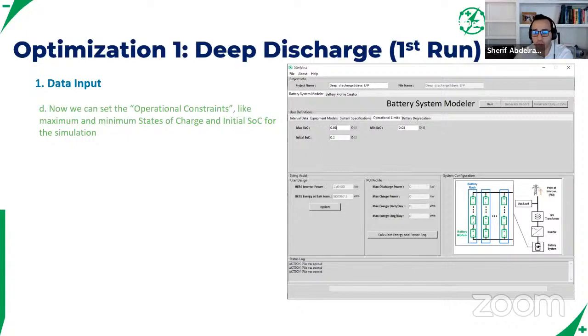That's why, with all LFP cells out there, it is very difficult to get the full range of that SOC range, unless you literally just performed a balancing cycle, which differs from one OEM to the other.